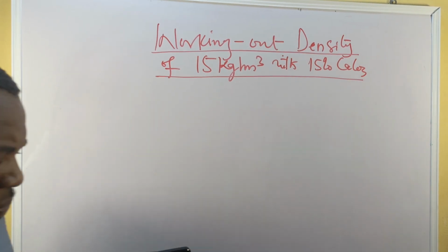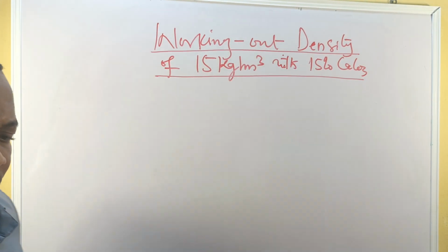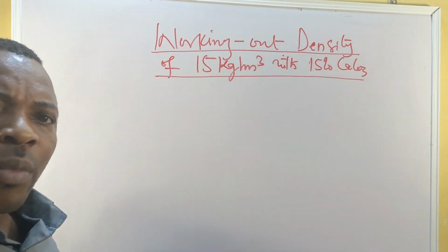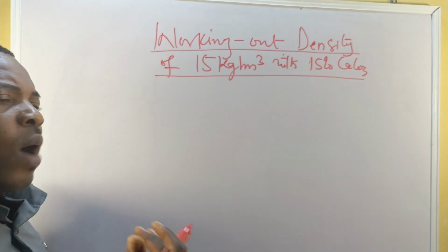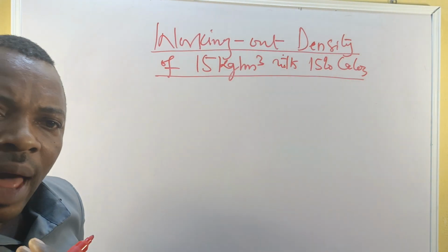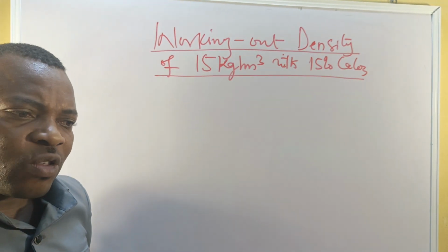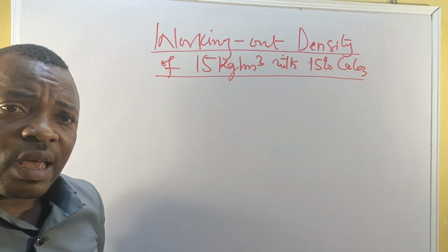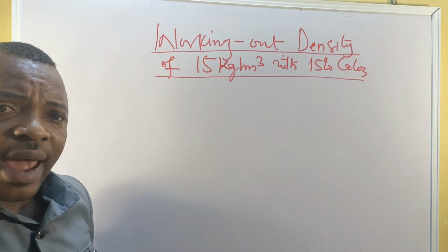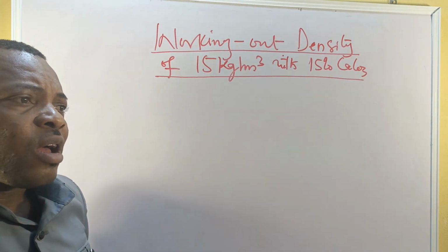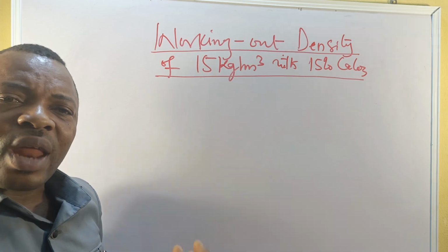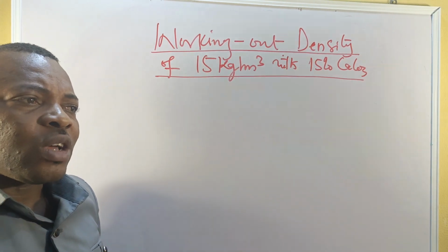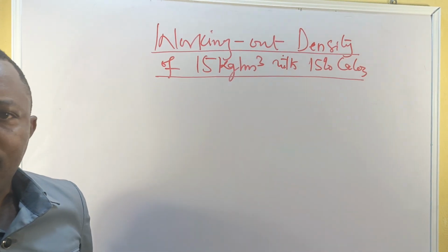Just like I said, there is no way you can copy formulation, especially for most of us who are using either box foam or continuous process, because the machine technology is not the same. So you have to be trained, understand the operational principle of your foaming plant machine, so that you're able to set a formulation that suits that technology.